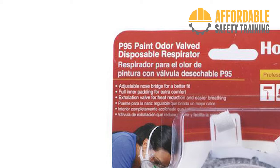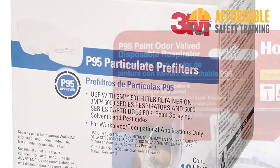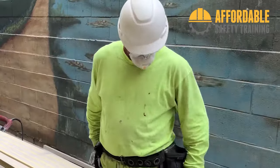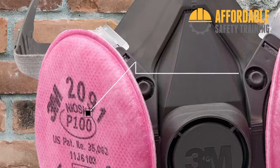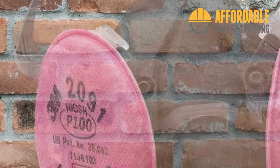Filter efficiencies are listed as part of their rating. It is usually listed next to the oil designator. A P95 respirator is oil-proof and 95% efficient. Filters with higher efficiencies provide better protection, but are more difficult to breathe through. The P100 on this filter means it is oil-proof, with a 100% efficiency.